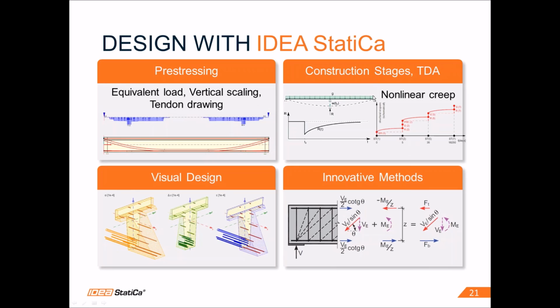In case of construction stages, we have time-dependent analysis, including the composite section and redistribution of the stresses. We can respect nonlinear creep in the analysis, which I have explained that it is a nice economic advantage.